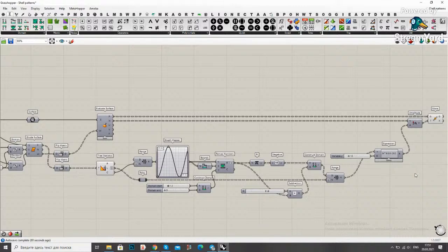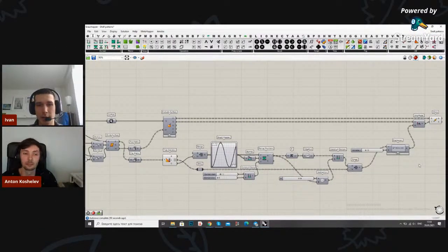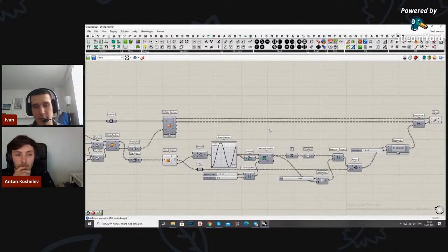Just to sum it up, what we are doing here is making sure that each branch has a certain amount of values applied to it, which allows us to have this kind of wave. That's why we don't flatten our data. We generate the values per each string of points, so we don't generate the whole points at once. We do it in a more structured way. As a general advice, it's always better not to flatten your data in Grasshopper unless you absolutely have to, which sometimes can be the case. It's quite often the case with meshes when you need to weld or join everything. But in this particular case, I don't recommend flattening the data at any point, because we need this data structure to achieve these complex results.